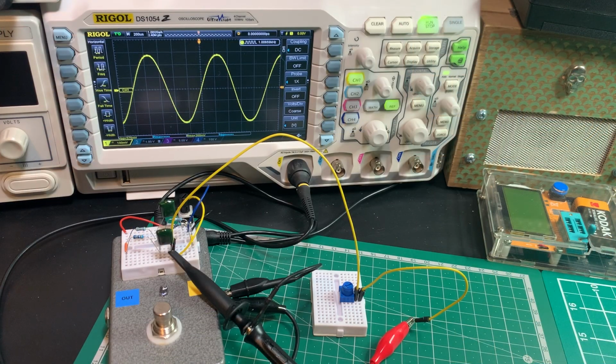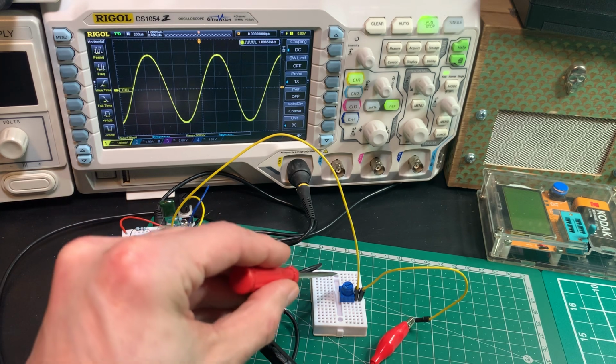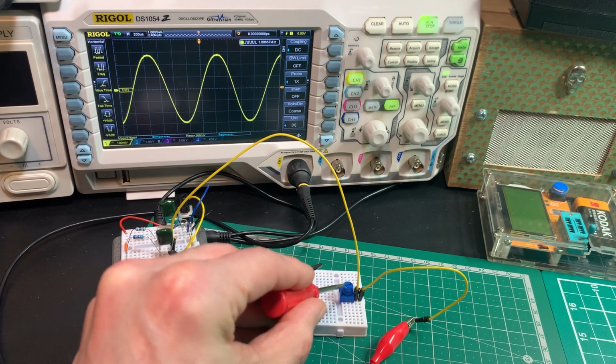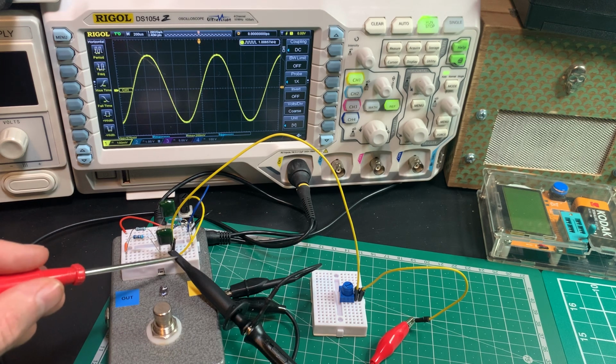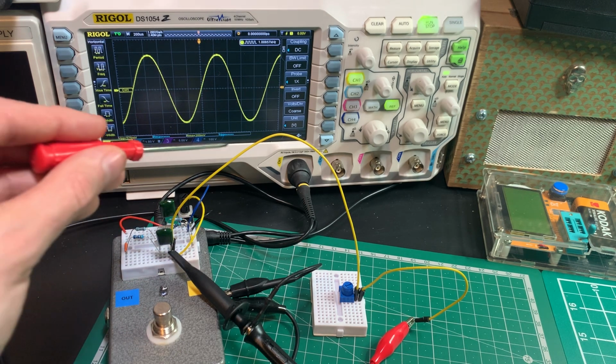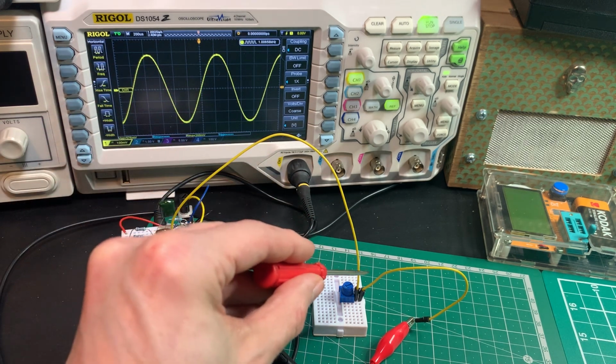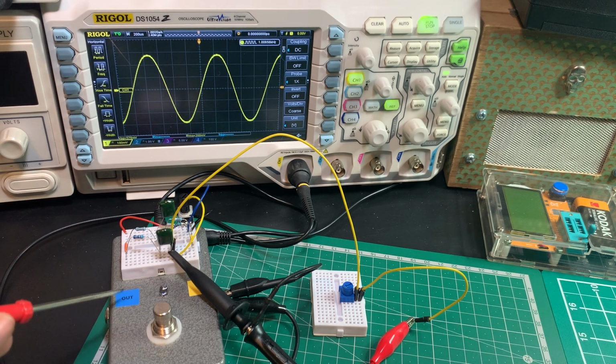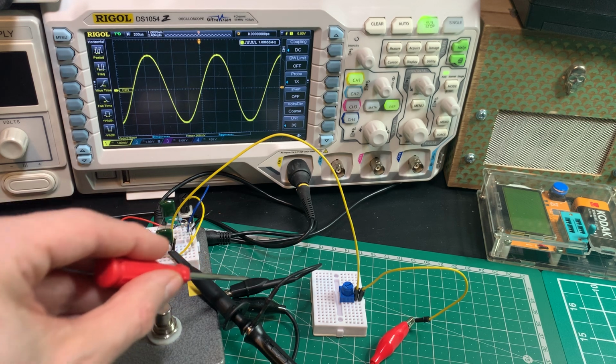So I've set up for measuring the input impedance with my potentiometer wired as a variable resistor here, and I'm measuring the input of my circuit, and this indeed is the input of the function generator going to the exact same place as the scope probe. Notice that I'm not using the output at all, and all my grounds are wired together.